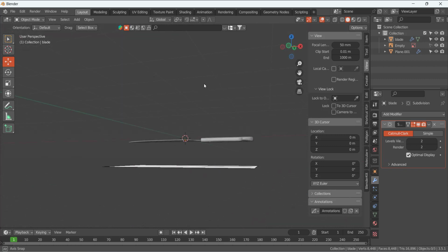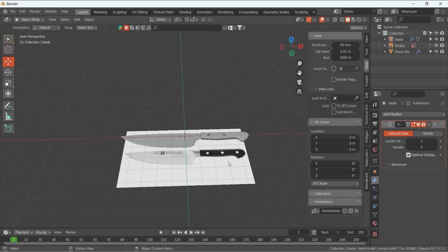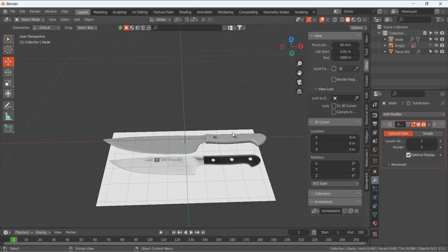So for me, now I'm going to stop because it's becoming lengthy. So this last hole is your assignment. You will get good with these loop tools and making the circle. How you can make the circle from some vertices you have, and how you can bridge them and make this hole. So you have to practice it.